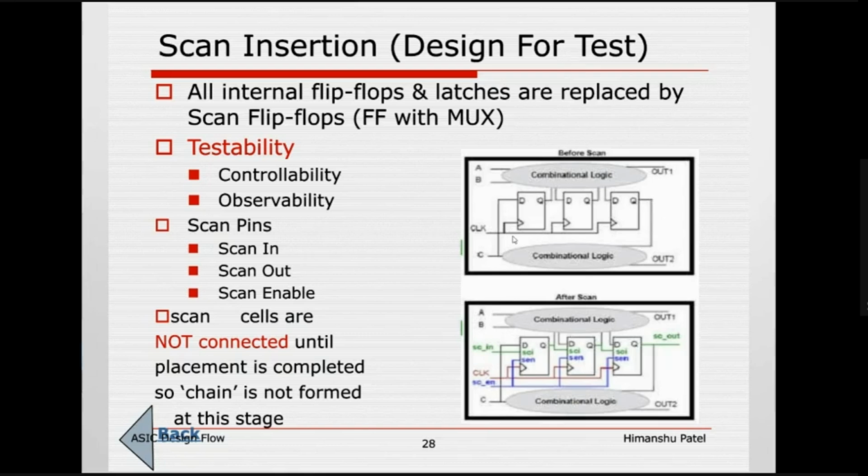Let's say a two input, one output mux. You have a single select line, which will select the A input or the B input of that mux. That's the way a mux behaves, right? You select the input pin based on the select line. Everybody agree on that?